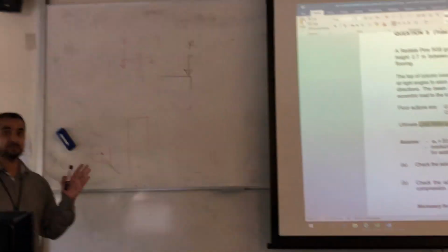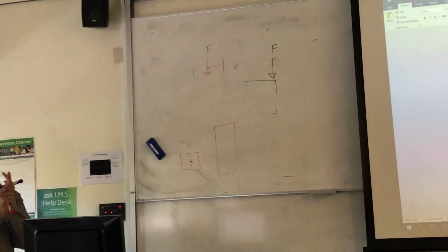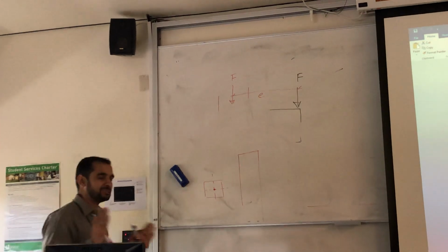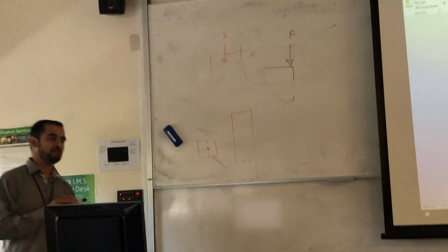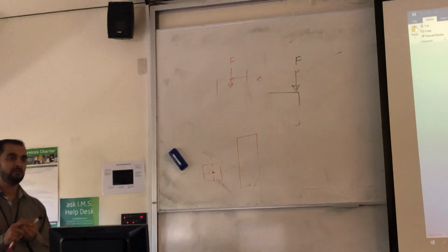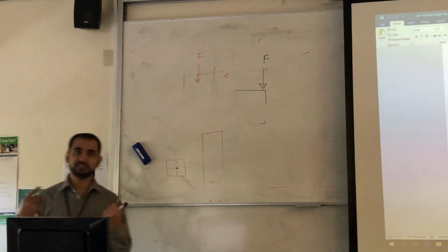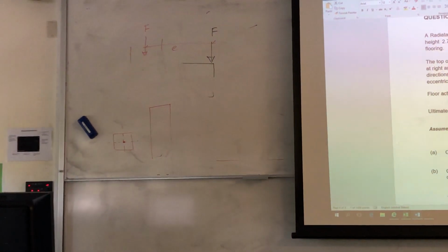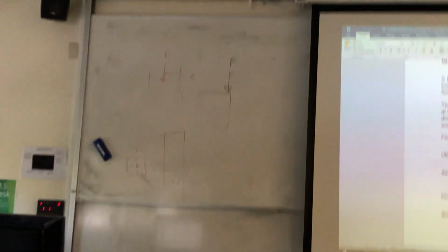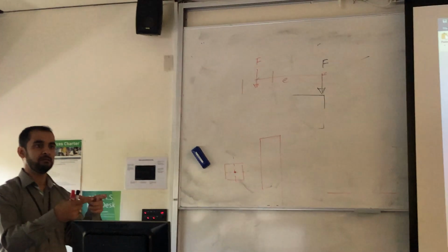And it's very important in buildings. Two things to remember: center of mass and center of stiffness. Stiffness means the resistance system, and mass means the weight of the building, and it's quite critical in earthquake. If we don't have a symmetric structure, and our lateral resistance system like shear walls or portal frames are not evenly distributed, then we have the center of stiffness to one side of the building, and the center of mass is usually in the center of the building, right?